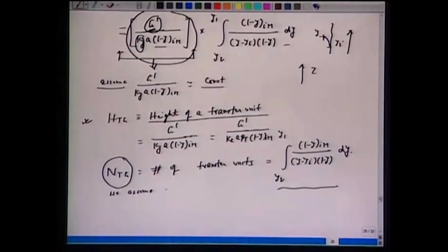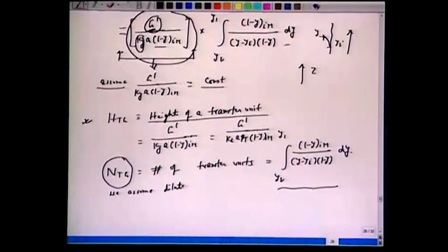So, if you have 1%, 2%, one can make this dilute gases assumption. That simplifies all our calculations here. Okay. So, with that assumption, let us assume dilute solutions, which is of course quite common. In that case, you can show that 1 minus ym is approximately 1.